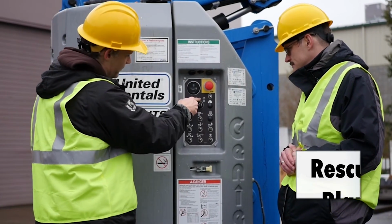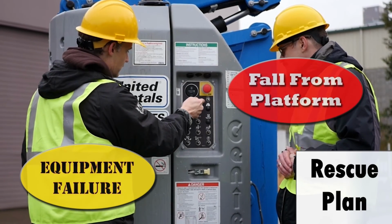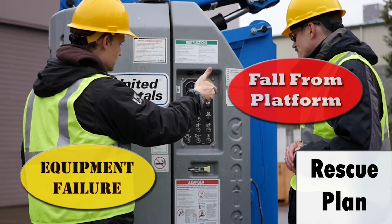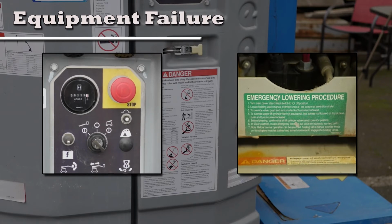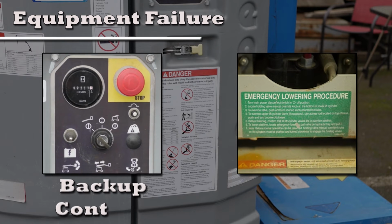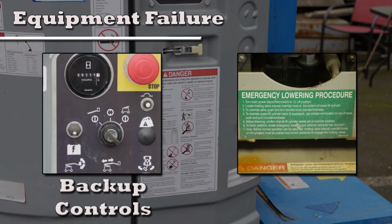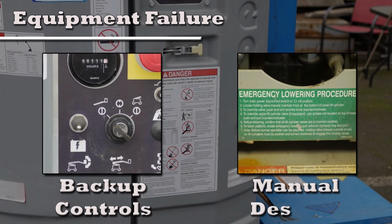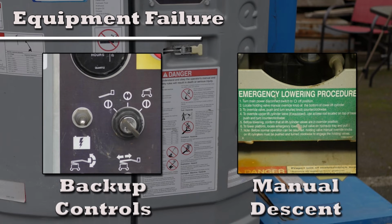Employers must have a rescue plan that covers equipment failure, and a fall from the platform. This plan must return a fallen, or stranded, worker to the ground safely, and quickly. For equipment failure, there are two major options. The operator can switch to the backup control system, and lower the platform to the ground. If the backup controls do not work, the secondary manual emergency descent controls can be utilized, to release the hydraulic pressure, and lower the platform.